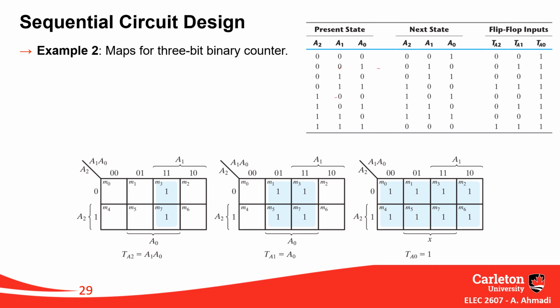And the beauty of this design is, if you have a higher number of bits in your counter, here I'm talking about a 3-bit counter, if you have 4-bit, 5-bit, 6-bit, you just add more T flip-flops and make your logic like this. For 4-bit, same thing: A0, A1, A2, and A3 will change when all three of A0, A1, A2 are 1, and so on. If you add more bits, similar logic will apply to your design, which makes the implementation simpler.